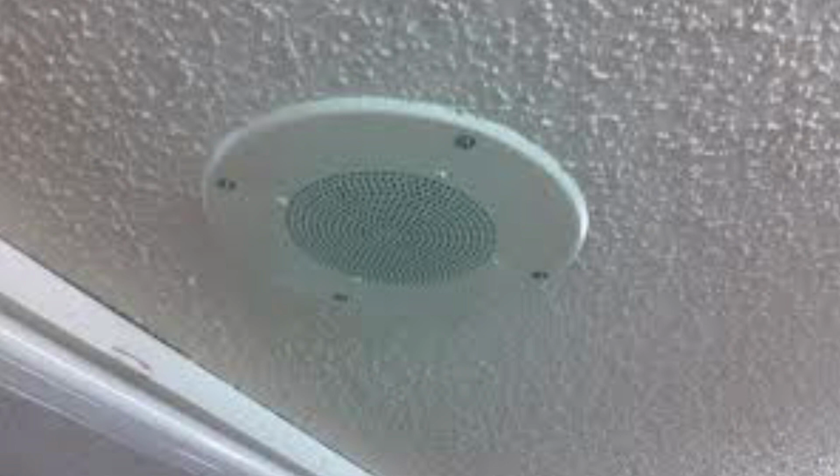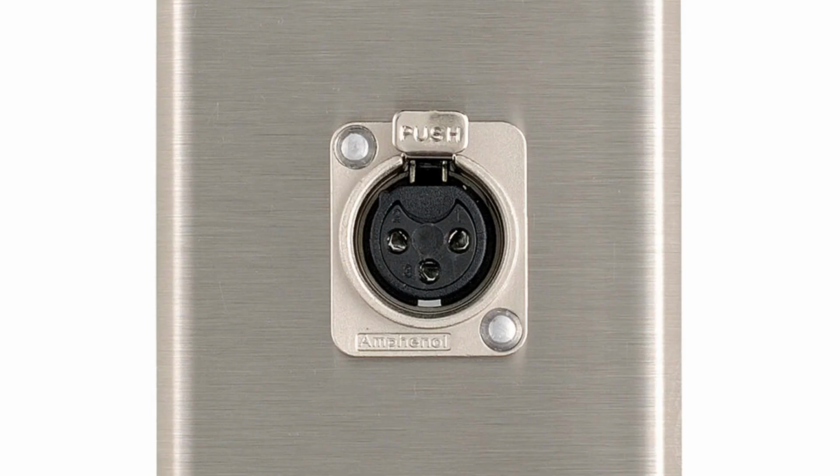If you have a much simpler scenario, say you're feeding this small staging mixer we described into a ceiling system, in other words, in a conference room that has speakers in the ceiling that have an amplifier located out of the room and out of your control, and all you have is a physical input connector in the room to it, you may at that point have to use the mixer's main output fader to control your room volume. In some basic AV setups, that's not an uncommon thing to do. It isn't necessarily desirable, but it's a workable solution.